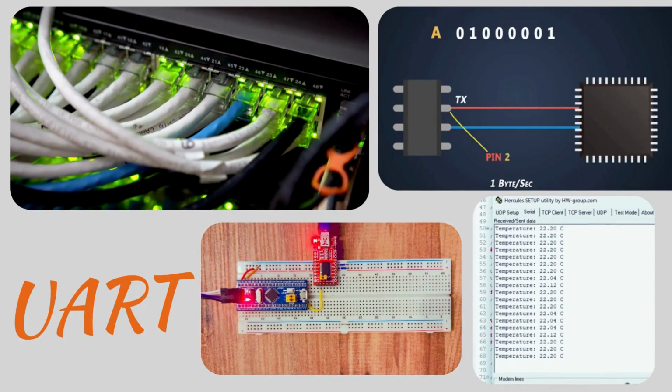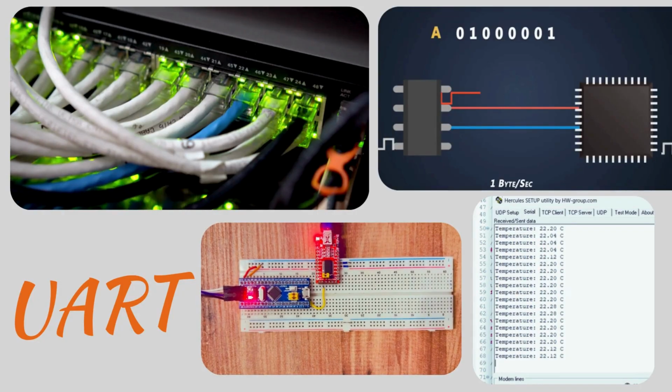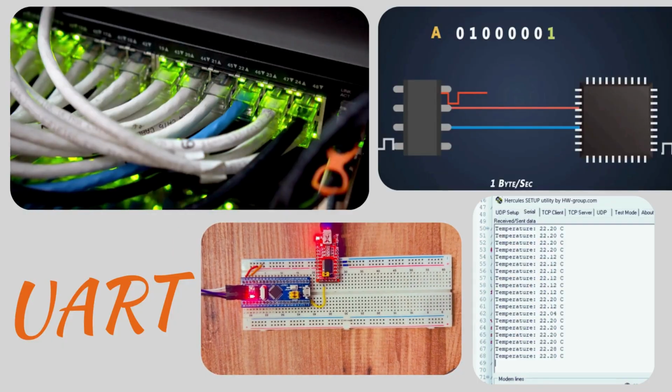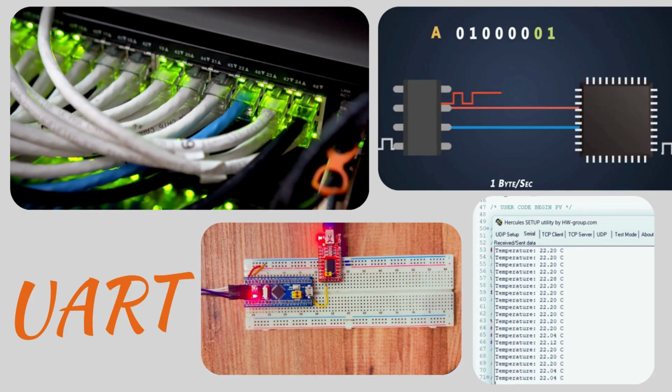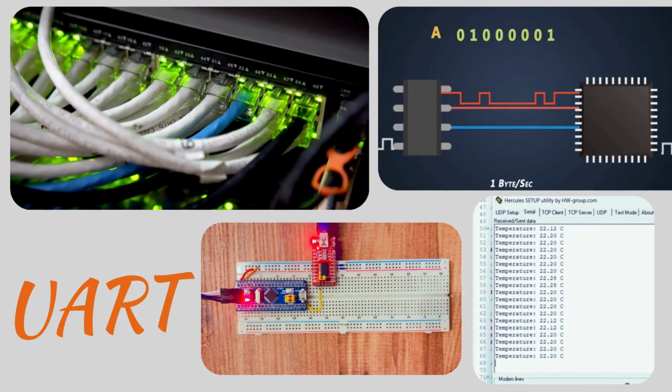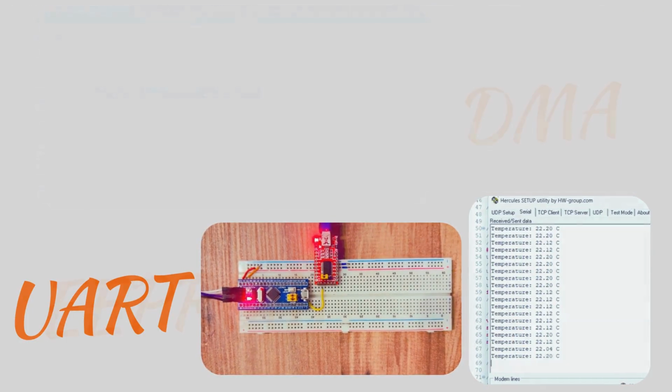With UART, you'll connect your board to your PC, sending and receiving data to monitor sensor values and build interactive projects. You'll also practice reading sensor datasheets like the DHT11 for temperature and humidity, or the ultrasonic sensor for distance to wire and configure them properly.